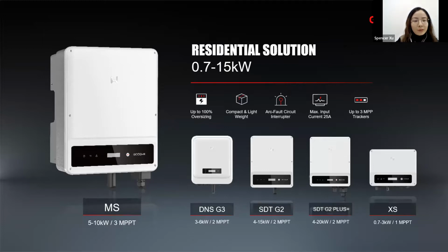And we also have the MS series, which is also single phase, but has 3 MPPTs, so it is more suitable for flexible system designs because it can be adapted to very complex rooftop situations.